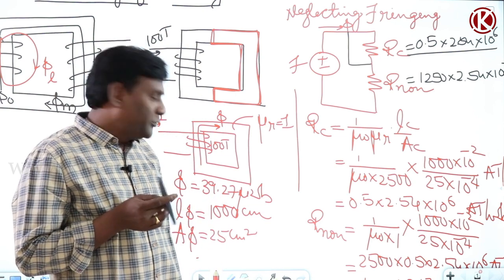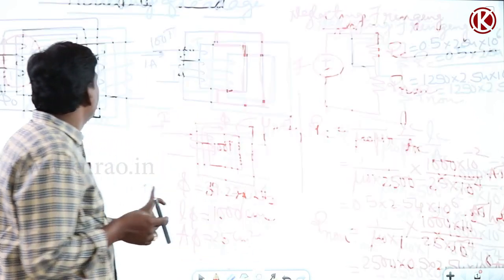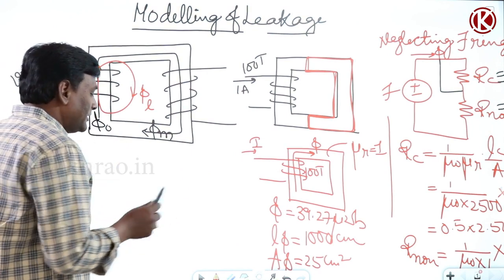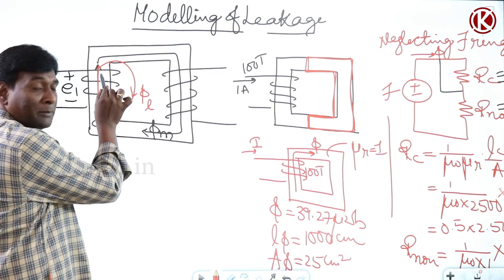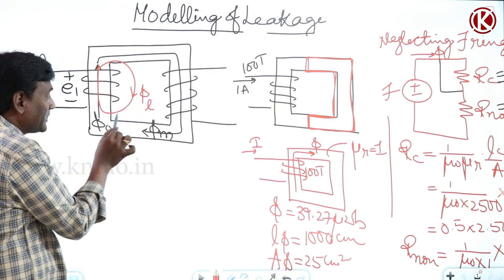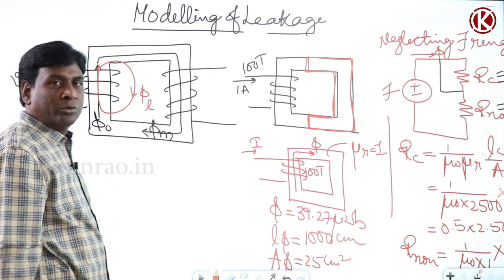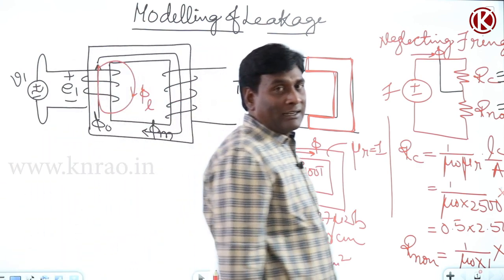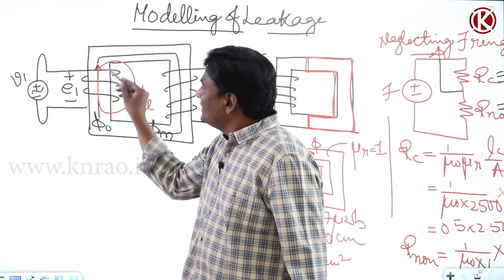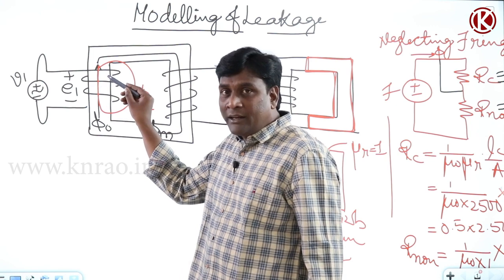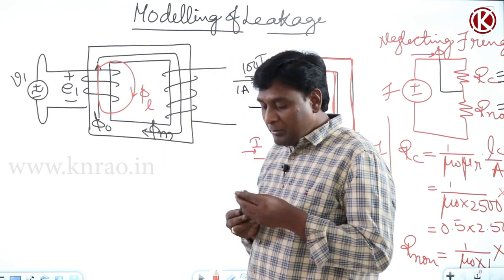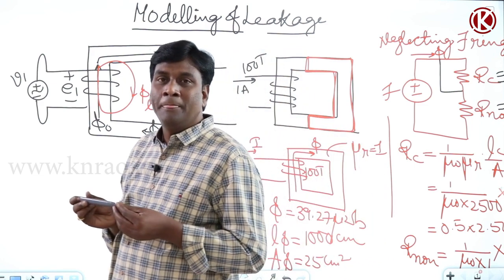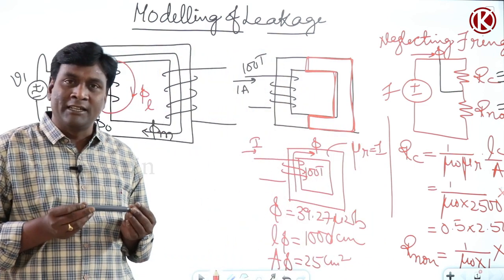What is that? If you think of leakage flux, the moment you think of leakage flux, around 50% of the flux path is going through non-magnetic material. Under those conditions, the flux path in magnetic material can be neglected and flux can be assumed as flowing through non-magnetic material only, making leakage a linear property.